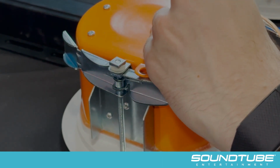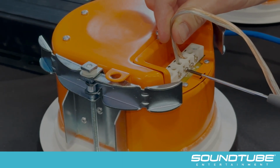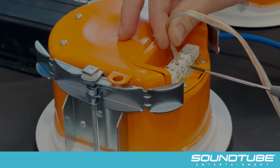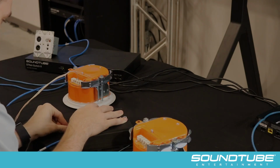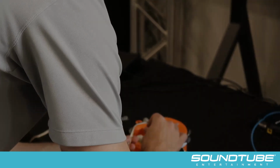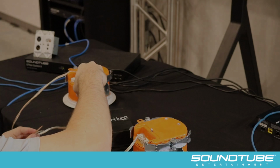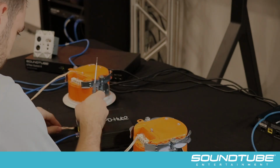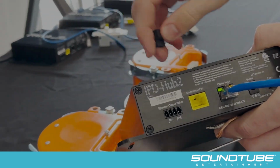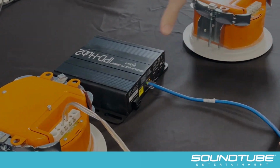This means that you must change the tap setting to the 8-ohm or 16-ohm bypass position. The SoundTube CM42 EZS ceiling speakers are 16-ohm speakers, meaning you can use up to 4 of them on each IPD-Hub 2. Speakers will wire just like traditional speakers with a traditional amp: positive to positive, negative to negative. We will put one speaker on output channel 1 and one speaker on output channel 2. Here you can see the output connections on the IPD-Hub 2. Channel 1 and channel 2, each with a positive and negative.